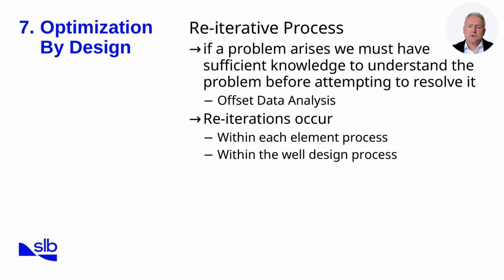Reiterations occur at two levels. First, within each element of the process. For example, rechecking casing design if new pore pressure data are revealed. Second, across the entire well design process, where early assumptions may need to be revisited as new information emerges.